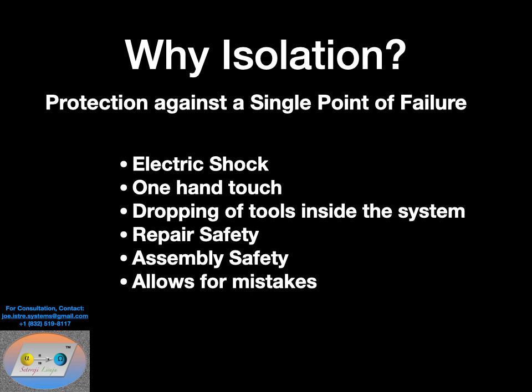So there's a few reasons for isolation, and it's all related to reducing the chances of electric shock and allowing for a single hand touch of the bus bars that are connected to the battery terminals or the battery electrodes. That way, when it's got to be assembled, right?